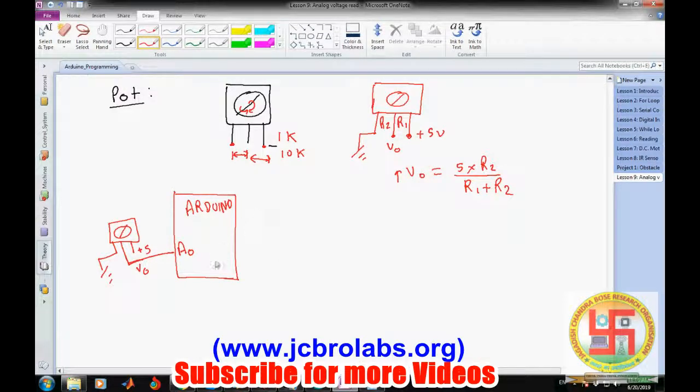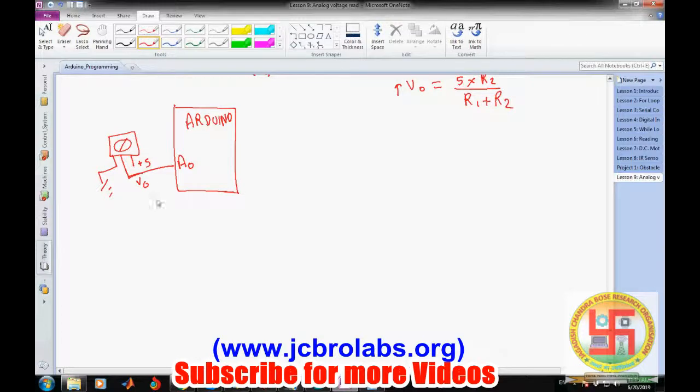Now we will write code to read that particular voltage so that we can check it on the terminal. Also we have applied a digital multimeter, which will be checking the voltage available here, and another point is connected to ground, so that we can verify that whatever voltage we read on the multimeter, nearly the same voltage should be shown on the computer. That way we can verify our code is correct and the program is working correctly.